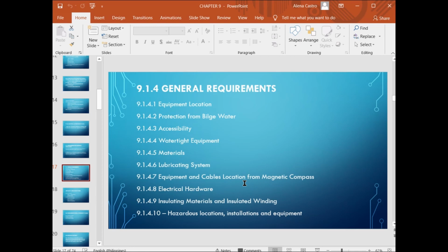All generators, motors, and electric couplings shall be so arranged that they cannot be damaged by bilge water, and if necessary, a watertight coaming shall be provided to form a well around the base of such equipment, with provisions for removing the water from the well, where power is used for propulsion. The equipment shall be so arranged that it will operate satisfactorily in the event of partial flooding of bilge water above the tank top up to the floor plate level.